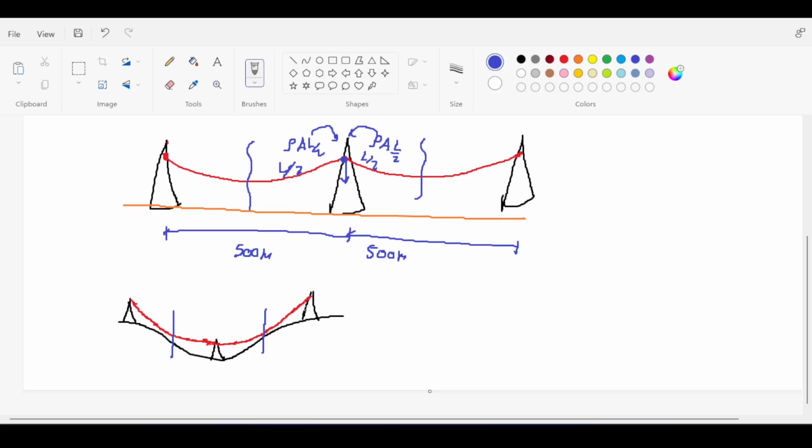You see, this tower will feel more tension than this tower because it's in the valley. Usually the towers on top will feel more tension than the towers on the bottom. But okay, how do I know this? There is something called the point of sag, which is the point where you reach the lowest altitude before the cable starts rising again.